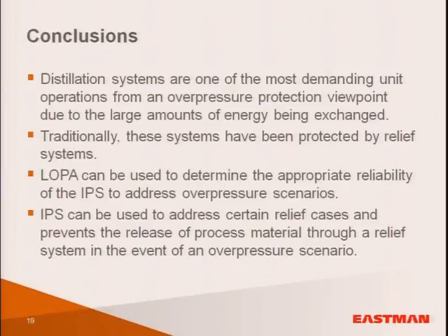However, due to the high vapor pressure of acetone in this case, that proved to be undesirable from a capital standpoint. So then we started looking at designing the relief system, and unfortunately, the reboiler needed to be very large because they were using potentially 15 psig steam as well in certain operating modes.